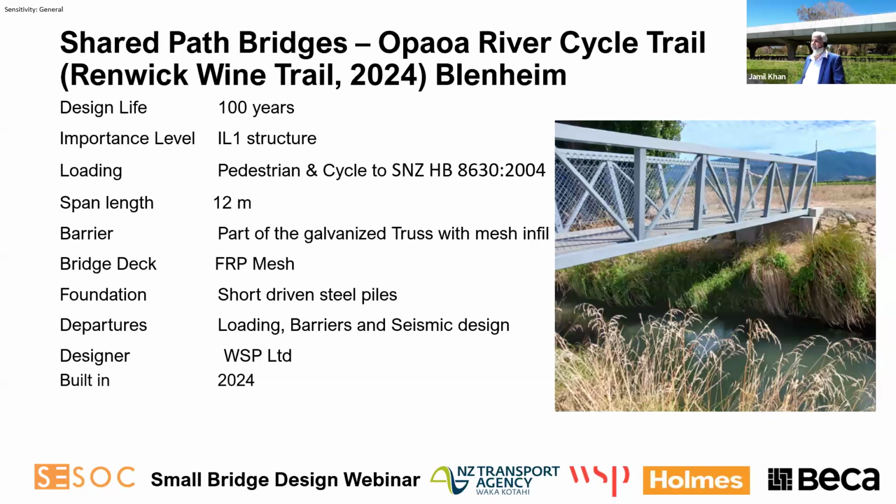This is another example, as we mentioned earlier, of using a different material. On this job they used a different designer and different material, and then used different standards, because this type of material is not covered in the bridge manual or other New Zealand standards. Foundation is short driven steel piles. Again, the departure for this one was applied for loading, barrier and seismic. So this is an example of a structure not designed for seismic. Design was WSP and it was built recently.